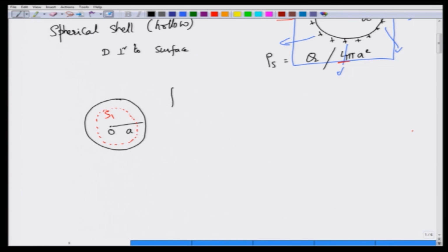Left hand side of Gauss law tells you that over the closed surface, if there was any D field over here, this must be equal to the total charge enclosed by the surface. Now, clearly the right hand side will be equal to 0 for this case. Why? Because this surface S1, you have to assume that this surface S1 is closed, of course it is closed, and then you have to see that there is actually no charge enclosed by this. Okay. So, there is no charge enclosed by the surface S1, and therefore, this will be equal to 0 on the surface S1 that we have considered.